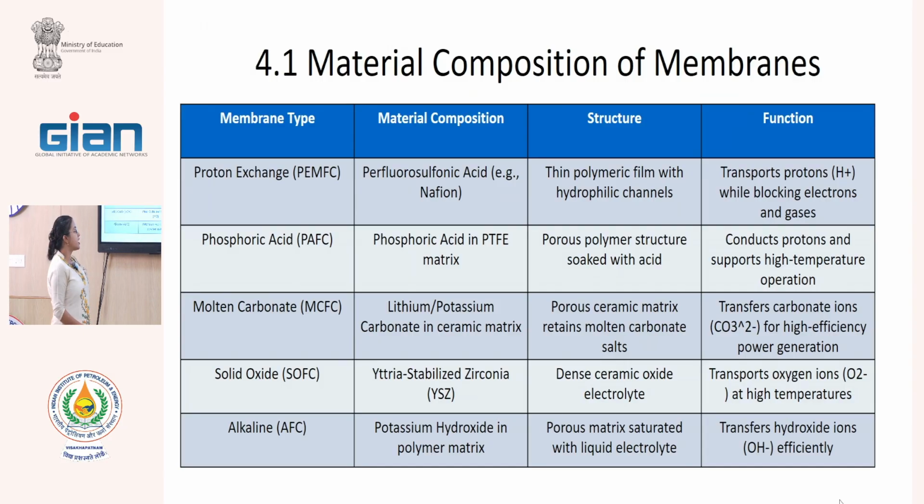Other than that, the structure of the membrane sometimes becomes important for a particular application, like the hydrophilic channels that I was explaining yesterday: the polymeric backbones make the two boundaries of your hydrophilic channel, and the side chains give you the functional hydrophilic space for the water to transport. So for that, a thin polymeric film is necessary for PEMFC.